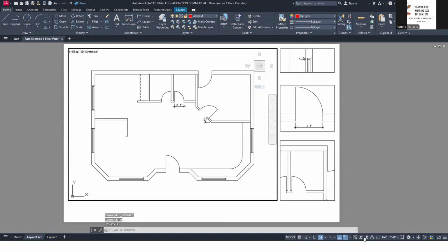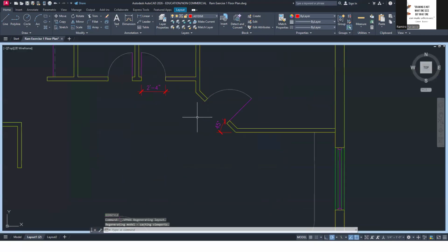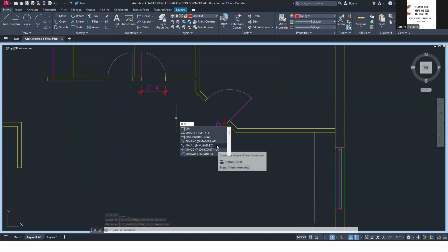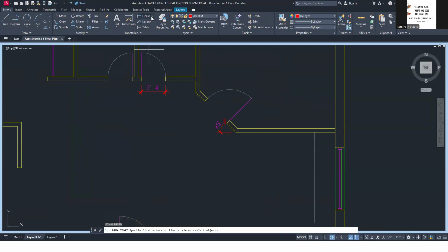These two buttons are turned off. This has 1/4:1 set. Okay. So maximize. And then type dim aligned. Okay. Dim aligned. It's also accessible here. Okay. And then you click on the 2 points that makes the angled line, and then you can place that.